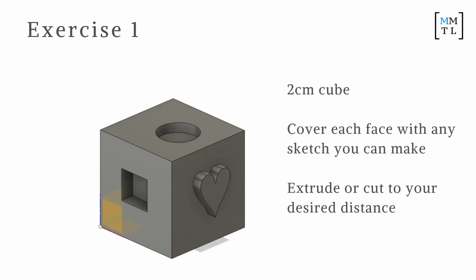Extrude command's easy. Make sure you set the profile, the shaded area, because that's what you're extruding. Once you finish the sketch, operate between 2D and 3D, and make sure you exit out of your sketch. Press finish sketch in order to extrude.